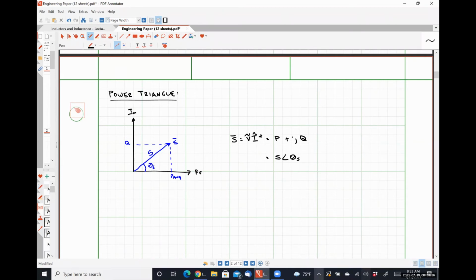All of these simply utilize Ohm's law in the RMS phasor domain. To be clear, what I'm talking about is V RMS phasor is equal to I RMS phasor times Z, which is the exact same relationship in the frequency domain and the exact same relationship in the time domain. Ohm's law is always V is equal to I times R. It's pretty great.